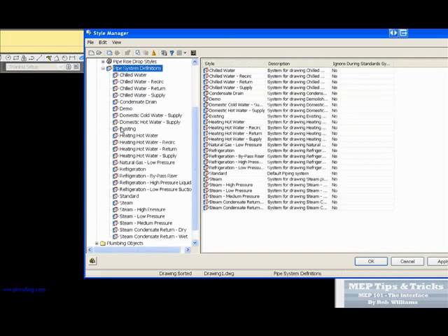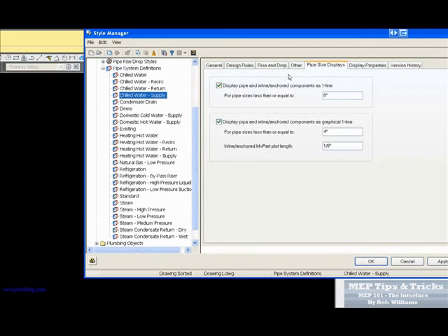Piping is the same way. You can come in here, and this is where you can set it up to draw 2D up until 8 inch. In this case, it's 8. You can always change that to 3. This is where we usually have it, and then it won't draw anything up to... Oh, turn that off. 3. Hit enter. That was chill water.